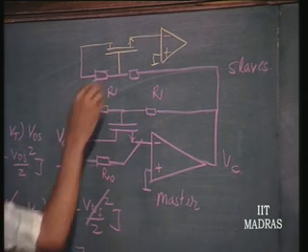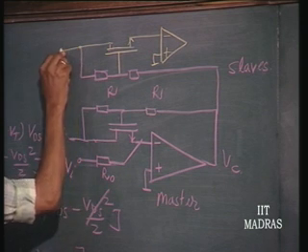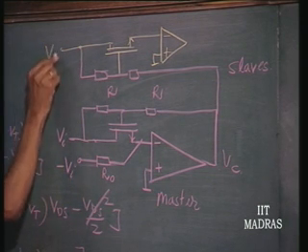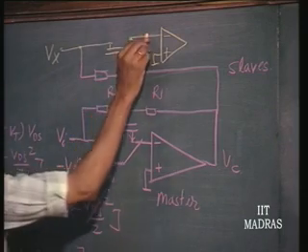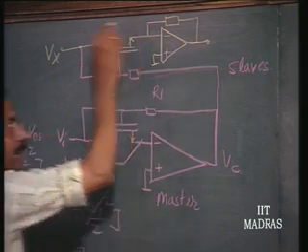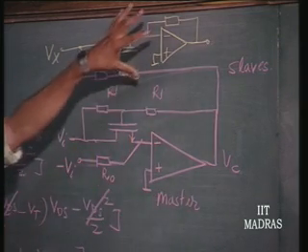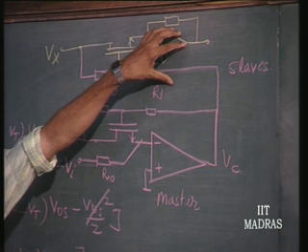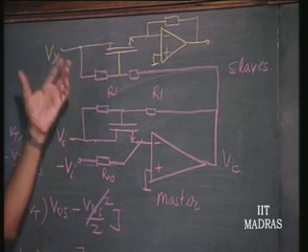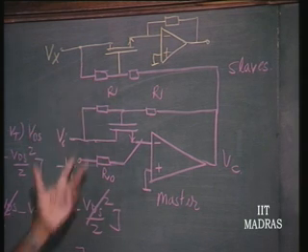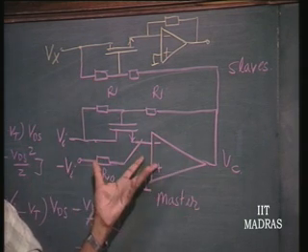So, then what happens? You can independently feed any voltage here, let us call this Vx, and put a negative feedback resistance. So, this is nothing but an inverting amplifier designed using the FET resistance, which has been made to be constant by another, independent negative feedback circuit.